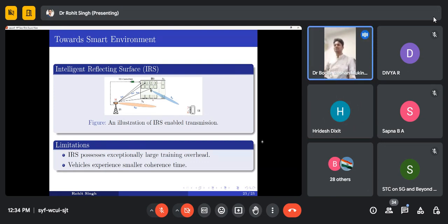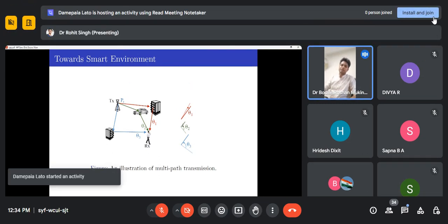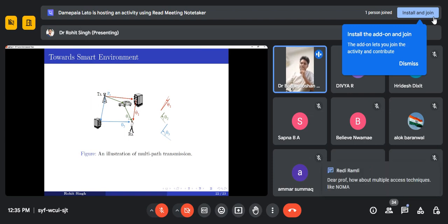Yes. So if you could see this figure, how many reflectors are there? Three. So in order to perform co-phasing, you need to control the angle of three reflectors. But for doing that, you need to have knowledge of which direction the reflectors are looking at this time. So to have that knowledge, you need to train the surface. The respective surface should have the knowledge in which direction the respective component is looking. This is known as training, and training is done one by one.